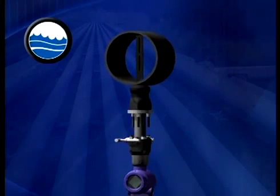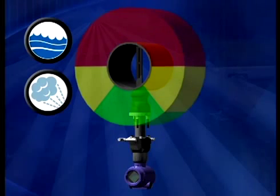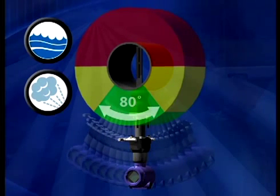In horizontal pipes for liquid or steam applications, mount the Annubar on the bottom of the pipe, within an 80-degree recommended zone. This allows any gas bubbles to vent up and away.